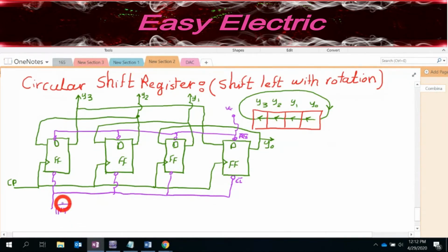What the initial pins mean is that this is somehow the reset. Before you start to work with these registers, just for a short time, you activate this. That means all conditions are 0. Then it goes back to 1, so this one is deactivated too. Then the shift register does its own job. So it should be able to do what we want.